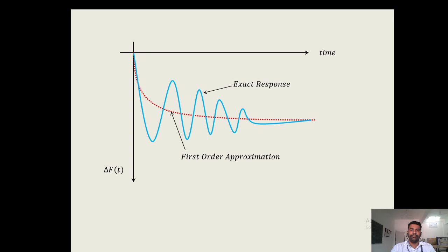It has some error, and the error is given by this much amount. So under dynamic response the error is this much amount. This error must be brought to 0, so that the frequency of the system will be 50 hertz. Now we will perform this experiment in the MATLAB simulating software.